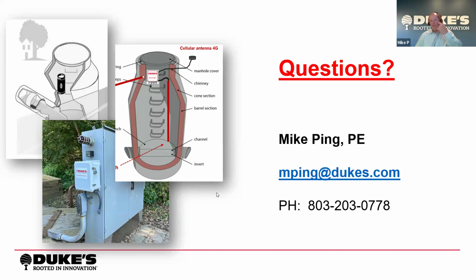Yeah, so the general approach, for me and speaking with people often, is marrying up an available budget with the pain, so to speak. Most utilities have a pretty good idea. Very few utilities have no idea where the I&I is. They can generally pare it down to a third or a half or two-thirds of their system. So that would be the starting point, eliminating some and starting out with a couple of data points to further reduce the area down. And then once it's reduced to a certain point, applying more resources.